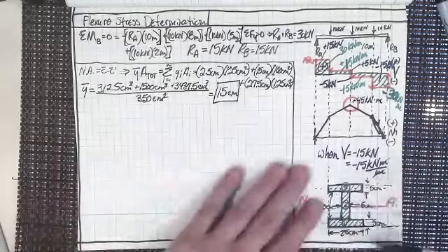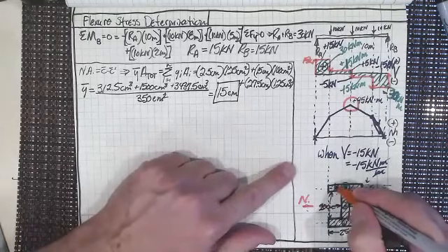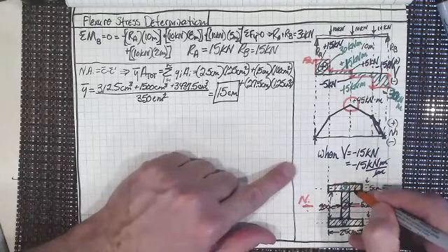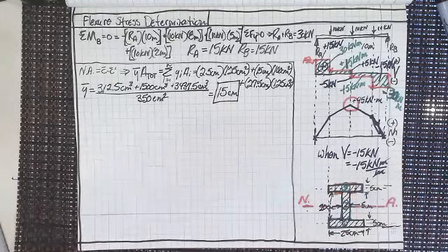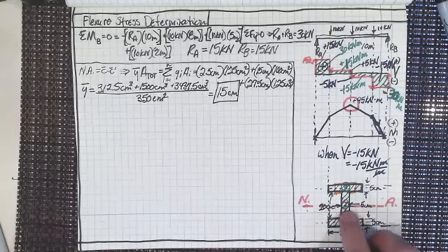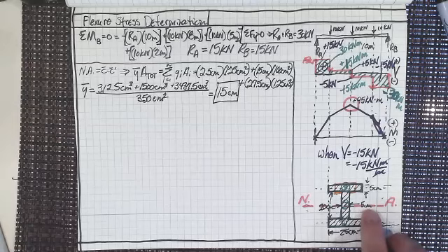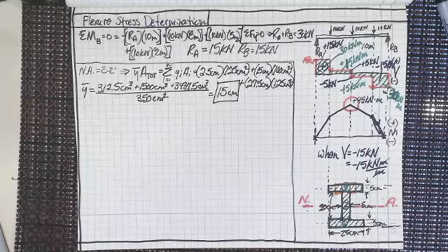Now, the same process. What if, like I said before, instead of it being like that, the top was shorter, like a railroad rail? Then you would find out that the neutral axis is a little bit lower than 15 centimeters, wouldn't you? And in fact, we'll probably do an example similar to that in the lecture after this, because I want to do a couple examples of flexure.